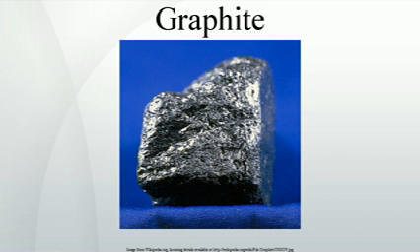The largest volume items, such as carbon magnesite bricks that contain only 15 to 25% graphite, usually contain too little graphite. However, some recycled carbon magnesite brick is used as the basis for furnace repair materials, and also crushed carbon magnesite brick is used in slag conditioners. While crucibles have a high graphite content, the volume of crucibles used and then recycled is very small. A high-quality flake graphite product that closely resembles natural flake graphite can be made from steel-making kish.